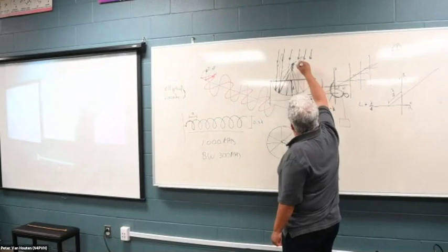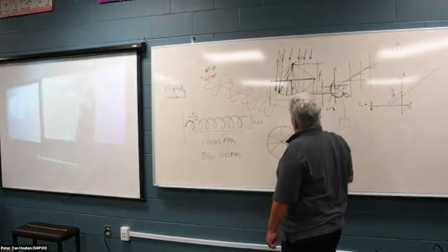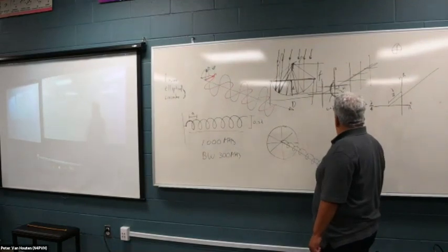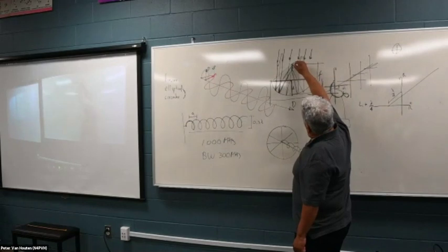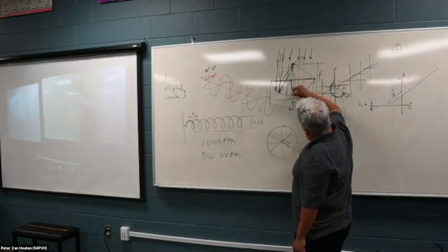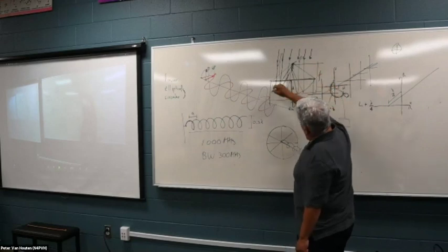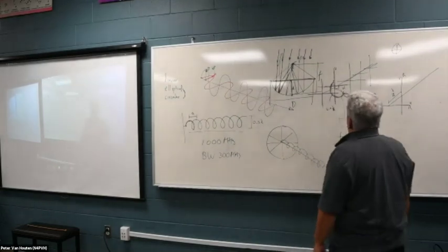And then the other one is F. An important parameter of design is F divided by D, meaning the focal distance, which is where my focus is, to the center of the dish, and the ratio between F and the diameter of the dish. Okay? That's a very important one.